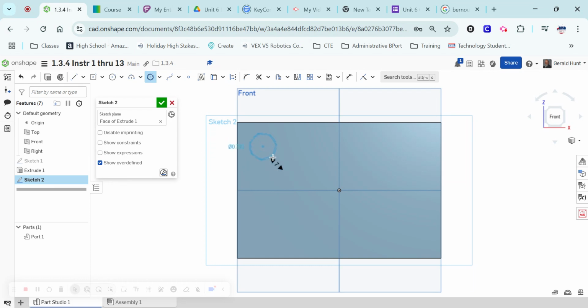And I'm going to draw it. And a pentagon has 5 sides, so I'm going to change it to 5. And my radius, remember, it's at a 0.35 radius. Notice it has our diameter symbol. So we need to double 0.35 and make it 0.7, so we have an accurate diameter.